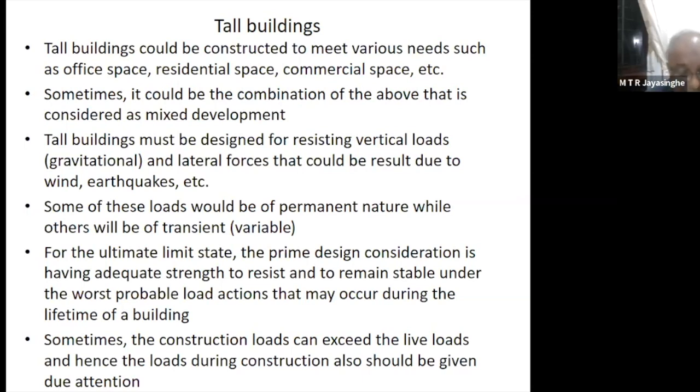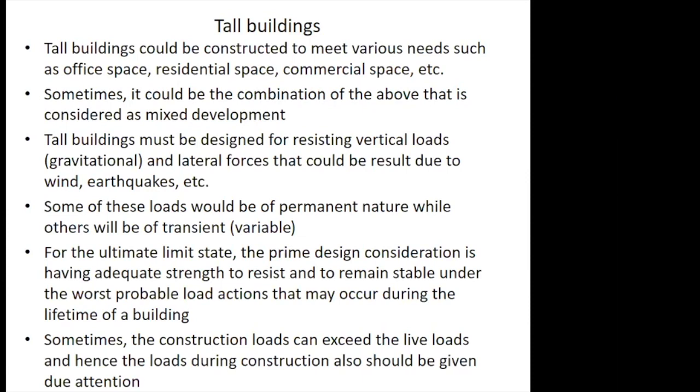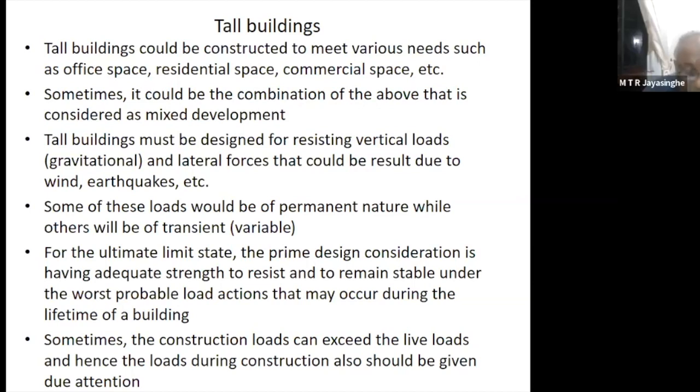Concrete containing fly ash is much better because it has a lower carbon footprint, it has low embodied energy, it has desirable properties, it is more corrosion resistant, and it could also be more sulfate resistant. Most importantly, fly ash containing concrete can be made slightly cheaper because fly ash can be obtained at a much lower cost than 1 kilogram of cement.